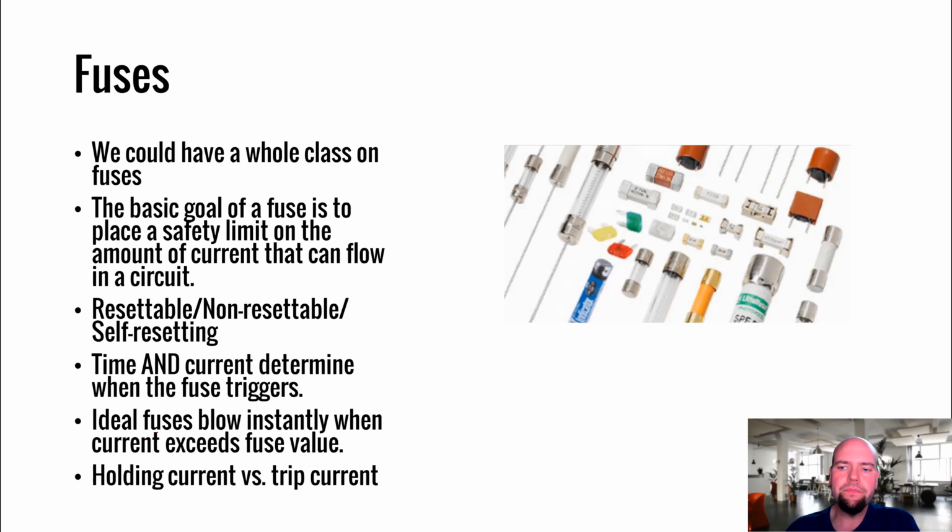We also have fusing to keep users safe. We have fusing to keep instrumentation safe. So even where it's not an issue of burning down the house, there can be an issue of if something's connected improperly and you have enough current flow that's going to damage the internal electronics in something, typically where you'll have a fuse. And sometimes a fuse is basically just a device that, if something breaks in the circuit because there's too much current, it's going to be the fuse. And so the fuse is something that's relatively cheap and replaceable, and it's the thing that's going to go first.